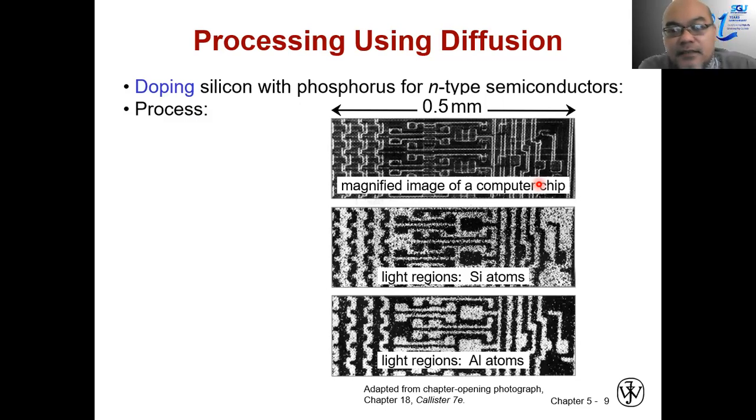One way to make silicon conductive at room temperature is by introducing impurities, what we call doping. We can make the silicon rich with negative charge carriers, with electrons, in which case we will dope it with phosphorus. Phosphorus is located at column 5. Or otherwise, we can make the silicon conduct holes instead, in which case the active charge carrier is positive charge, the hole. In this case, we can dope the silicon with boron from column 3 of the periodic table.